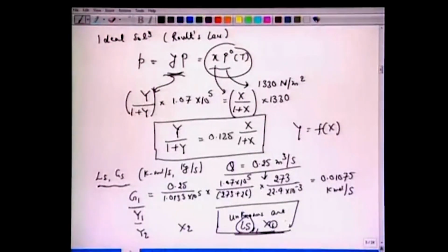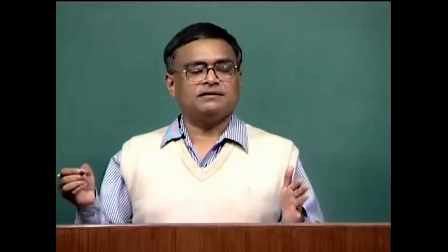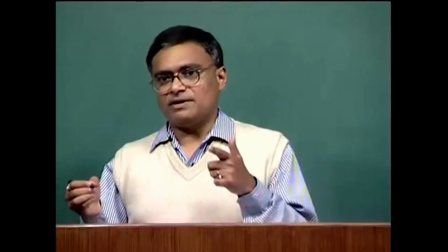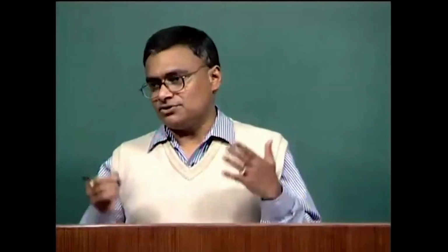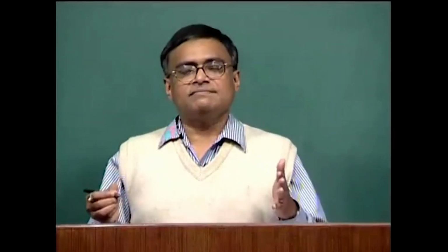Now we are in a position. After doing this small calculation, with whatever is given to us and whatever we are supposed to determine, we can draw graphically. Remember, not necessarily do we have to solve graphically. One can write down these two equations for the operating line and the equilibrium curve and solve by simple calculations. But it's a good idea to draw graphically and mark those points at least qualitatively.